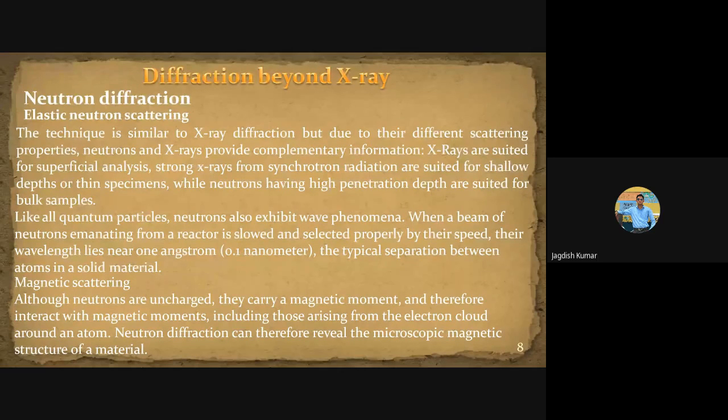So that area of cross section will be increasing, and that will affect the shape of the peaks in the X-rays. There are certain shape parameters when we do Rietveld refinement, and those are helpful in determining all those things. Mainly the shape of the peak will be affected because of that. Atoms won't be vibrating so rigorously that even the interplanar spacing will change. No, that is not going to happen. So practically, most of the times the peak shape parameters are affected, and that is what we can employ.